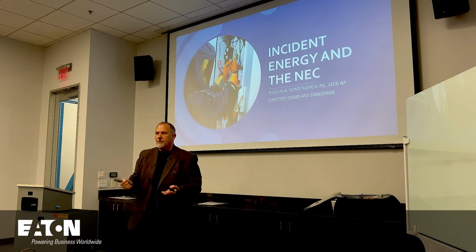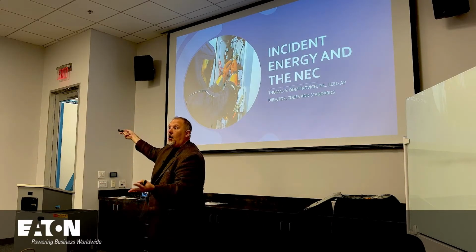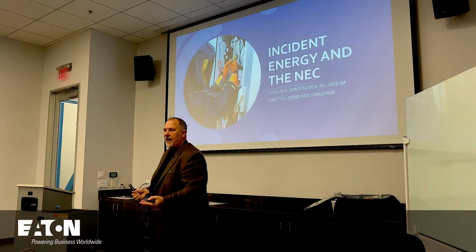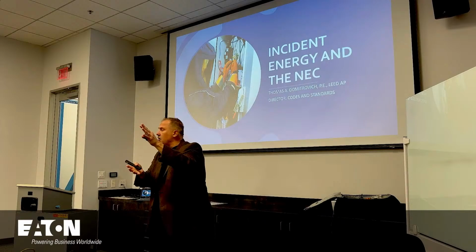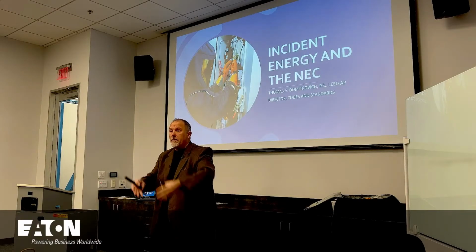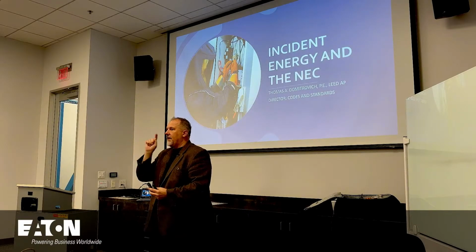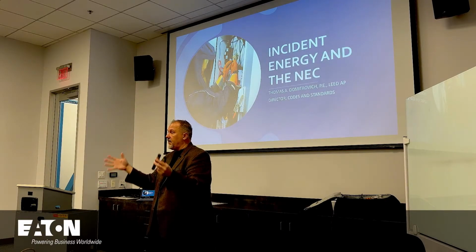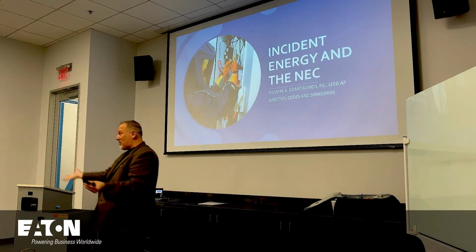But then someone said, boy, there's this guy down the ways who has a ground fault all the time, and he doesn't have the loss of all the voltage issues, of all the transient events that are going on in the facility. He doesn't have as much equipment damage. We sort of like those grounded systems. But then they realized that once you ground that system and you have a grounded system, that first fault is no longer a gimme, it's a doozy, right?